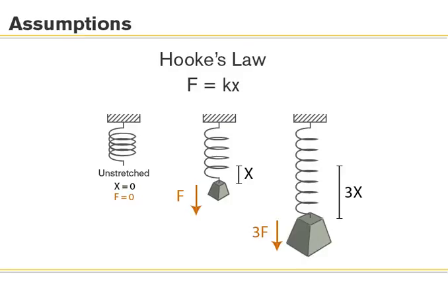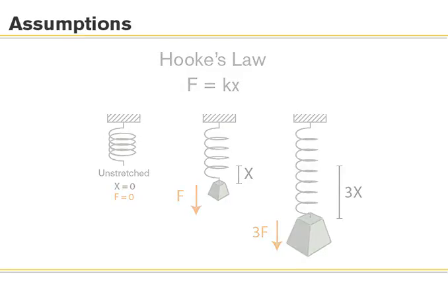A material exhibiting this behavior for most of its useful life, such as steel, is said to be a linear material. Most steels and aluminum alloys can be assumed linear in typical applications. Rubber is a common example of a nonlinear material. Nonlinear material behavior is not supported in Express and will not be discussed in this tutorial.